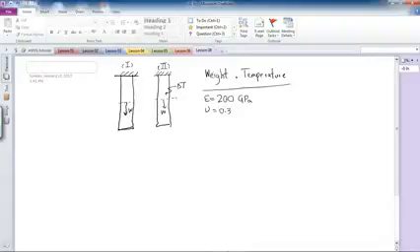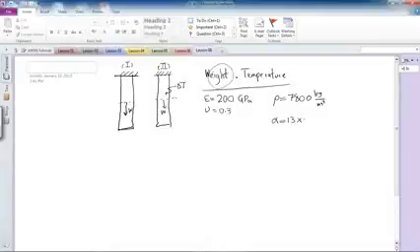But then, because I'm going with weight, and what I define will be a volume, in order to get the mass to analyze the effect of its weight, I'm going to apply density. For steel, it's almost 7,800 kilograms per cubic meters. And because I'm going to also examine the effects of temperature on this beam, I'm going to need to provide ANSYS with the coefficient of thermal expansion alpha, which for steel I've read to be 13 times 10 to the minus 6.